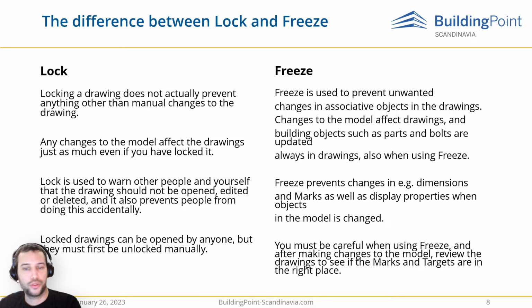Using freeze, you should be careful. And when you have made changes to the model, have a look at your drawing, make sure that it looks like it should, and all the marks and dimensions, and so on, are in the right place.